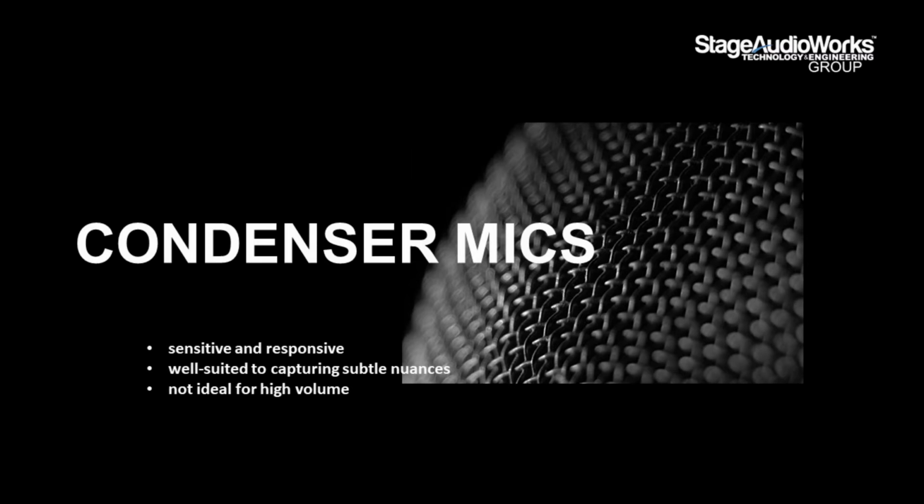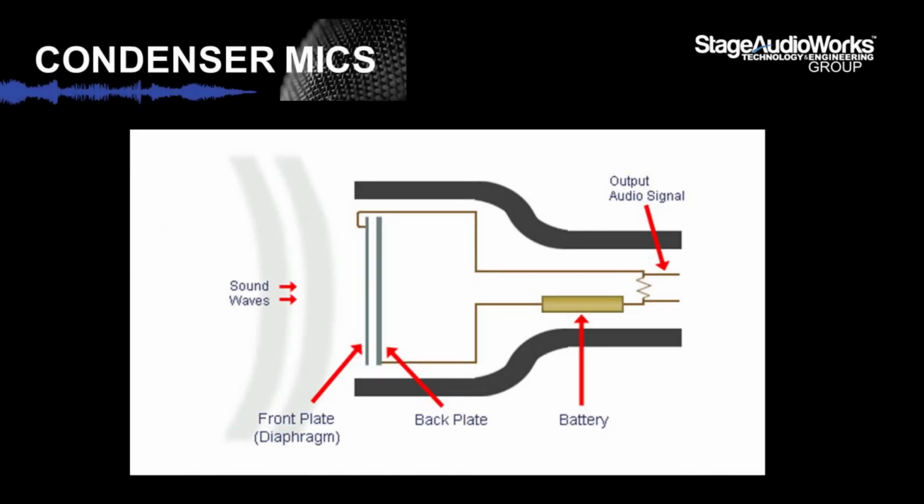If we look at the cross section into how it works, condenser mics have two plates with a voltage between them. One of these plates is made of very light material and acts as the diaphragm. When struck by sound waves coming in, the diaphragm vibrates, changing the distance between the two plates and therefore changing the capacitance.